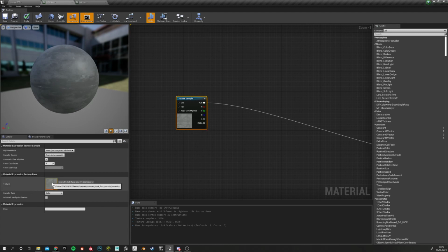But this texture is 2K. If we turn this into a parameter, every time you load up and make a copy, this will be the default. 2K uses a lot of memory and is not very efficient, because what's the point of having 2K here when we just need something so the error goes away, because you need to have some sort of connection.